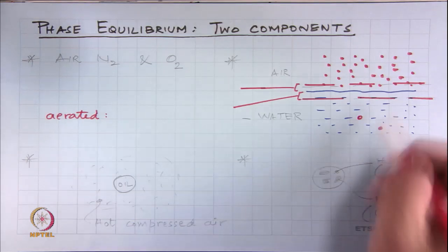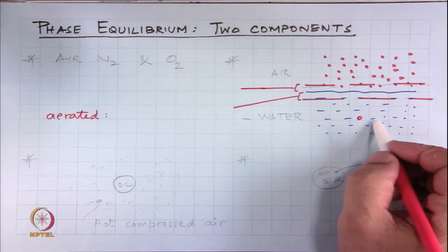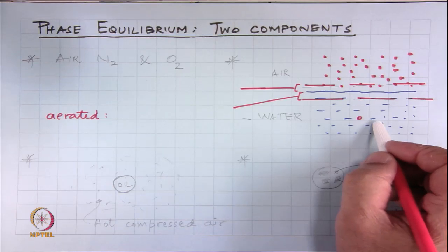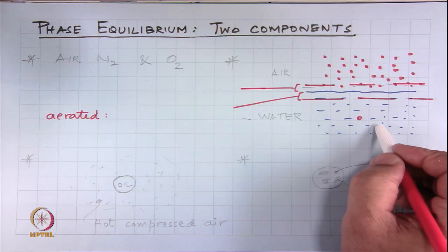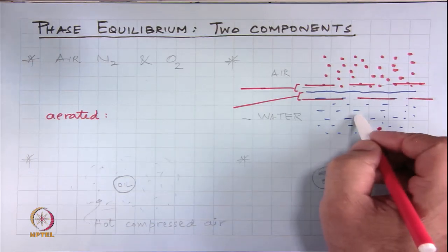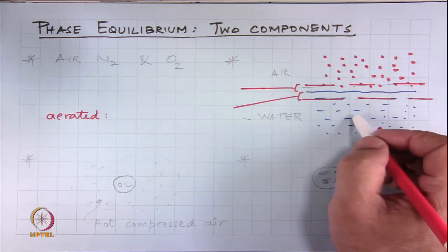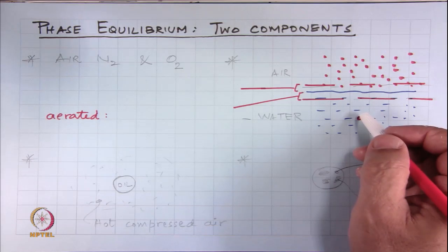It is also a fact that the water we drink has air in it, but if the same water were used in any process where steam is used, like the Rankine cycle you learnt, then as you heat it, what will happen to this oxygen and nitrogen? If they begin to get out, the oxygen will react with many of the elements which form the material of the tubes and surfaces, and that is not nice.